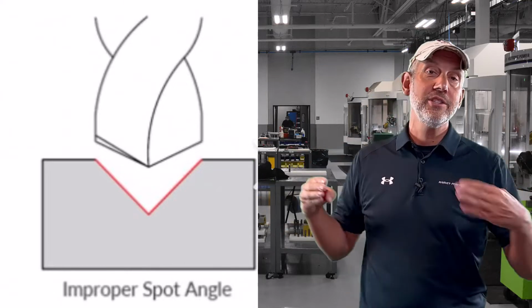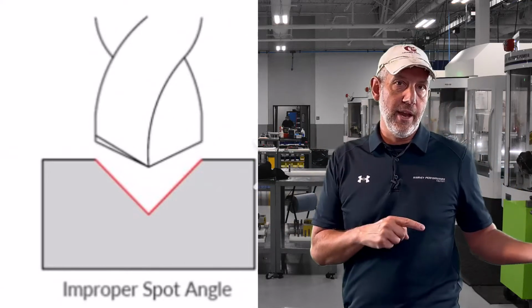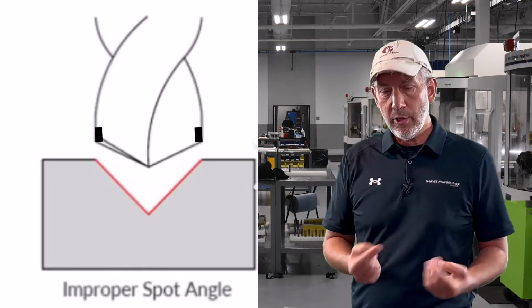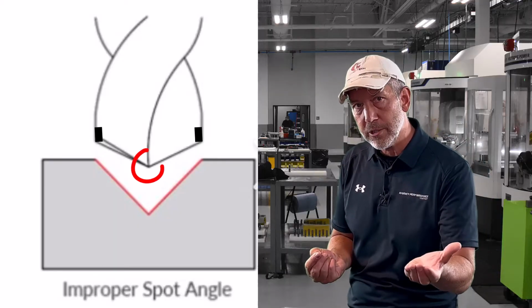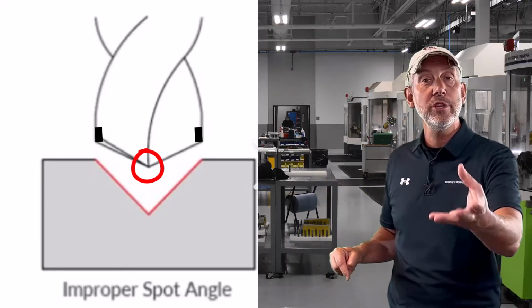So the outside edges of a carbide drill do not break, do not fracture, and do not wear down. You want the point to do the work first. The point is where it's going to guide it in. So when you're using a spotting drill, make sure it's flatter than the point that you're using, because you want to drive off that point and you want to give it a good start in the hole, and that's going to help you get a better quality hole.